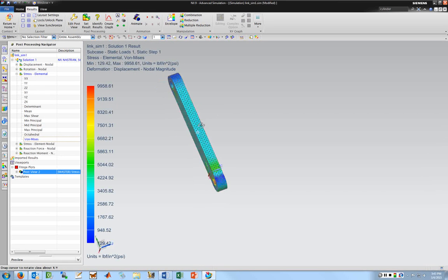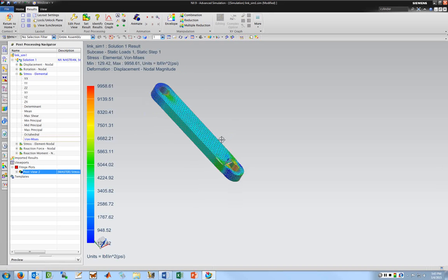I'm still not anywhere close. So this is 6061. This is 10,000 pounds per square inch on the max end of that, compared to a yield. I think it's 40,000 pounds per square inch for 6061. So that's really not an issue at all for this. But if this was higher, if you needed a higher load and you're actually really worried about this thing failing like you are for almost all FEAs, then you are going to have to do a mesh sensitivity, cutting the mesh size in half, running this thing again, and seeing how things change, and trying to get your loads as closely correlated with how it would be loaded in the real world.